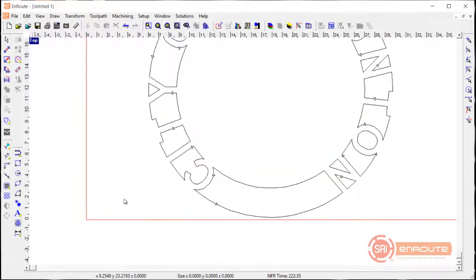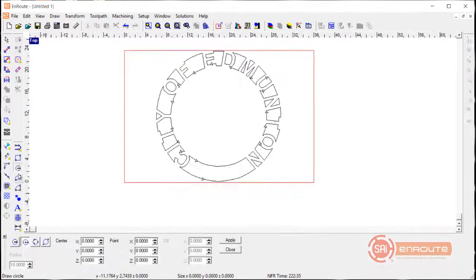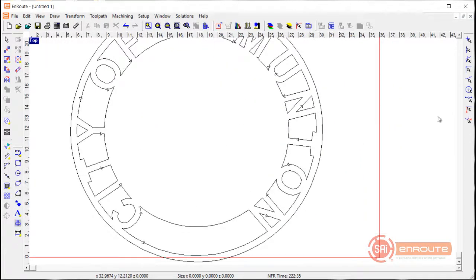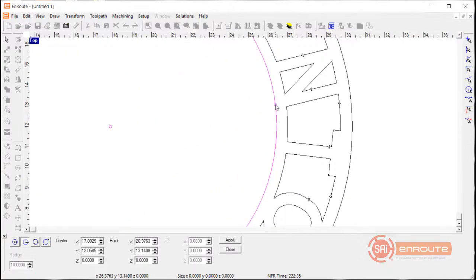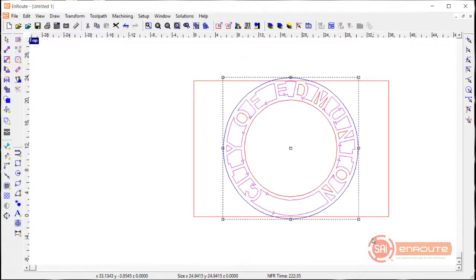All right, now we've gone all the way, so we've created the inner and outer parts here. Now we can draw a circle, so I'm going to go to the Draw Arc tool here. I'm going to turn on my Snap to Center of Arc for a second, just to get that started, and then I'll turn it off. Now I can just kind of eye this up a little bit. And I'm going to do this one more time. So we'll go to the circle tool, turn on the center part, come here and turn it off. And I could be more specific, of course, if I wanted to take the time to measure it really carefully.